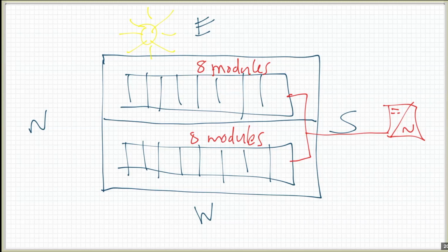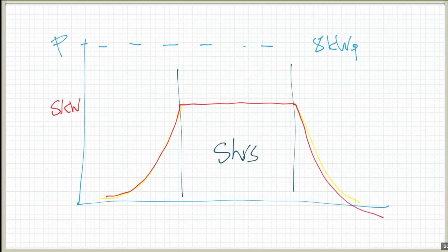Great. All right. So a question that came up in forums recently was about calculating the VOC max of a PV array, the open circuit voltage maximum. How high can it go, and how do you calculate it, and what are the regulatory limits? So this is to do with Australian and New Zealand standards. So the VOC, so voltage open circuit max, is the maximum under any operating conditions. It's not the nameplate rating of a panel.